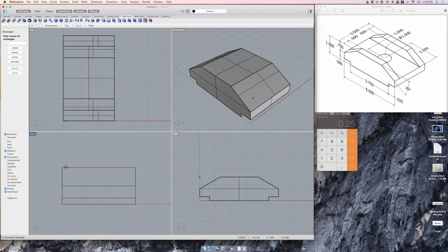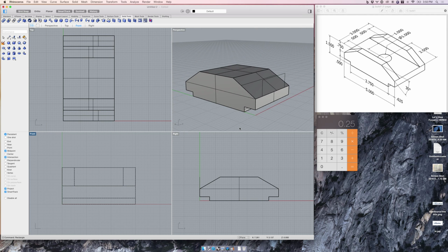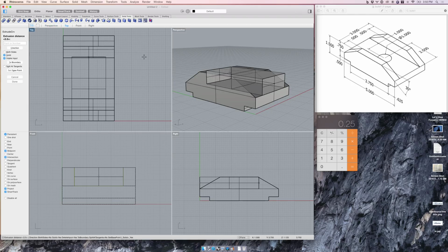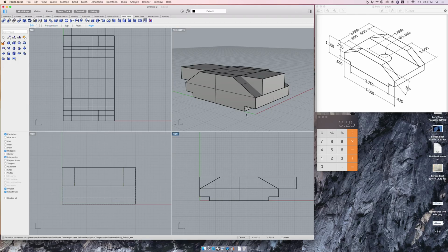First I want to move a 1/2 inch. So there's 1/8 and 1/4, 3/8 and 1/2. 1/2, beautiful. And then I'm going to go down 1/4, 1/2, 3/4, and come over to 1/2. I'm going to check that. And then, yes, you know what I'm going to do. I'm going to create a curve, a solid out of that, I'm going to extrude it all the way through.